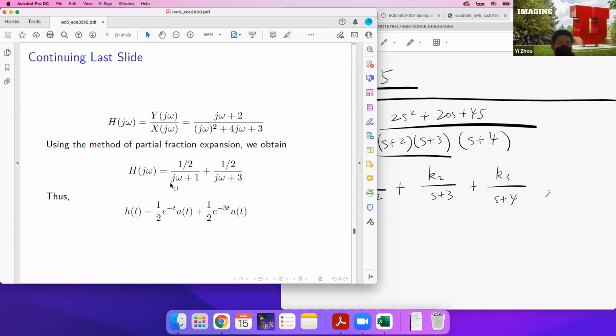So in this case, for this specific spectrum, after the partial fraction expansion, this specific spectrum is associated with this standard exponential signal from that table. Okay. So in this way, you can completely avoid calculating Fourier transforms or inverse transforms by hand. That's the idea. For this type of problems, you don't have to do any Fourier transform calculations.